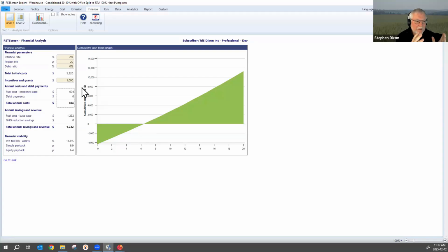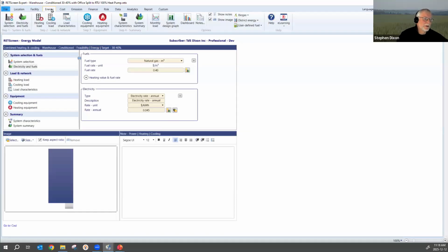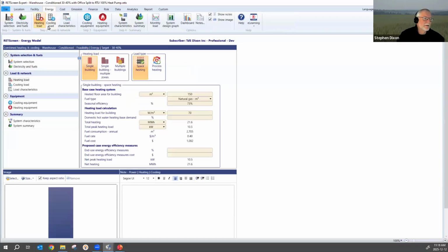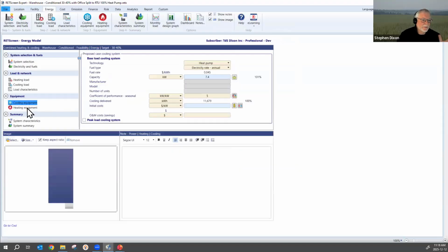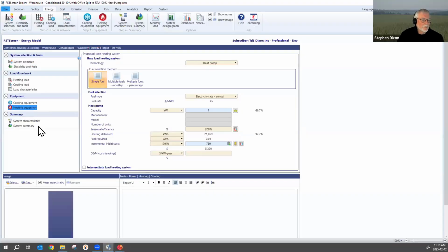We're getting there. But the idea here is we want to be able to come up with this idea. I'm going to take part of the system, I'm going to electrify it. I don't necessarily need to meter it. I can do some simple modeling with RETScreen, determine the loads in that area, and preliminarily design a system, right? The heating load, the cooling load, what I'm going to replace it with, the heat pump of a specific size. Now, I still have to go out and say, okay, can I buy a heat pump that's going to have these characteristics? And we may find we have to buy more cooling capacity than heating capacity. But again, that's a detail beyond what we're going to cover today.